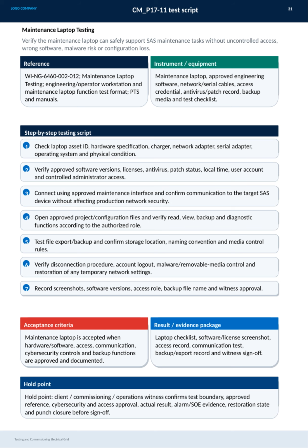Finally, a hold point requires client, commissioning, or operations witnesses to validate the entire test boundary, references, cybersecurity and access approvals, actual results, alarms, restoration state, and punch list closure before sign-off. This ensures the maintenance laptop meets rigorous safety and operational standards.